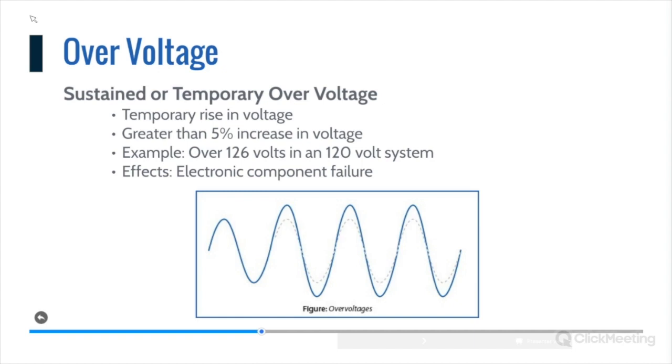Instead of a system that's set at 120 volts as far as usable voltage, they set their system to run at 126 volts because they know there's going to be a dip in the system. Well, now you're going to get that rebound effect that every day, certain times of the day, in the evenings in particular, all of a sudden your load demand goes down. So that 126 volt voltage threshold is going to now be exceeded. And so you're regularly going to run out of tolerance.